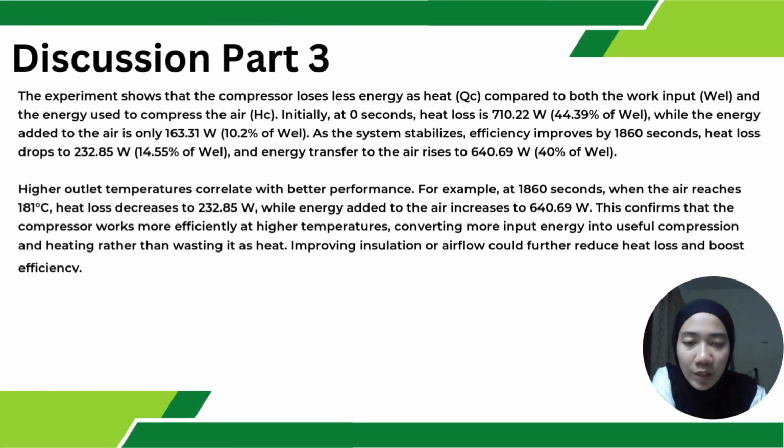So basically, the experiment shows that the compressor loses less energy as heat QC compared to both the work input WEL and the energy used to compress the air HC. Initially, at 0 seconds, heat loss is 710.22 watt, equals 44.39% of WEL, while the energy added to the air is only 163.31 watt, equals 10.2% of WEL.